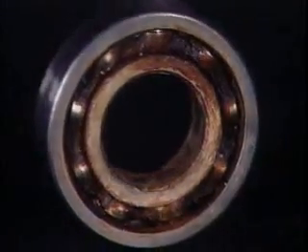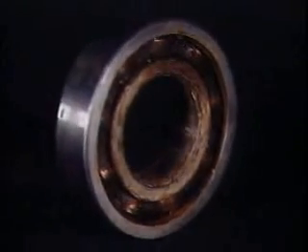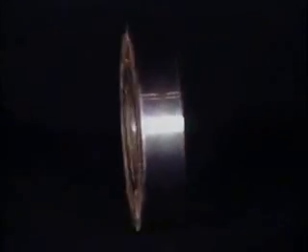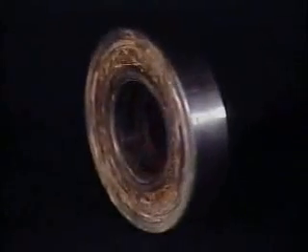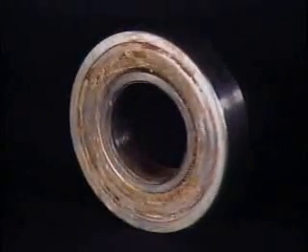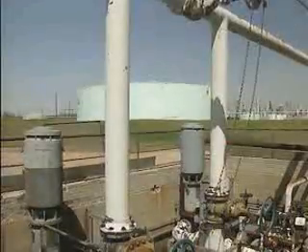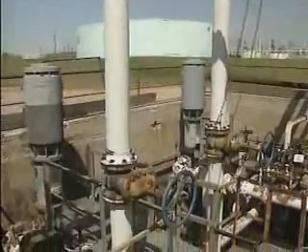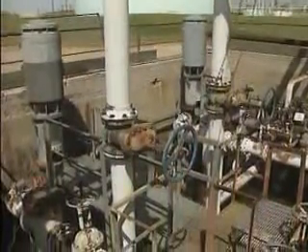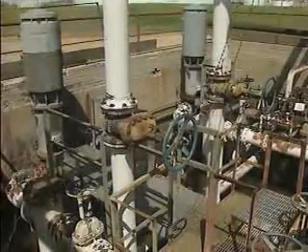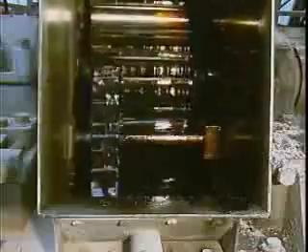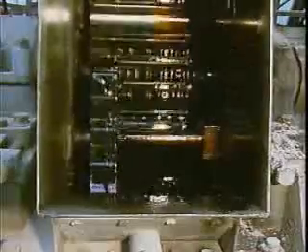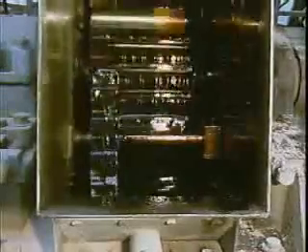Oxidation causes chemical changes that destroy a lubricant's effectiveness and lead to the creation of deposits such as sludge and varnish. Oxidation also produces acids that cause rust and corrosion. The oxidation process is normally slow, and over time, most lubricants do tend to oxidize. Oxidation can speed up, however, if the lubricant splashes around excessively or if it's exposed to high temperatures.